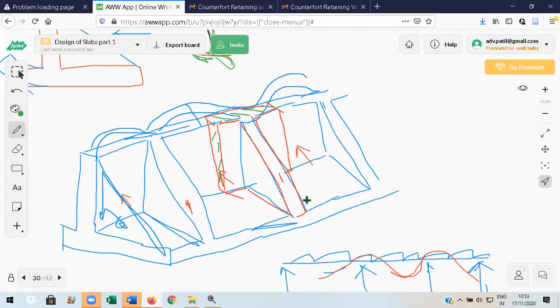Now, whatever this wedge is, it is triangular. Actually it is the rib of the T-beam. This is the flange of the T-beam. Rib is different from whatever you have seen so far. Normally, you may feel that it should have been like this. This is a horizontal line here. Then it ends here only, like this. It is a rectangular prism here. If this is a rectangular prism, you will easily appreciate it is a T-beam rib. This is the flange of the T-beam.